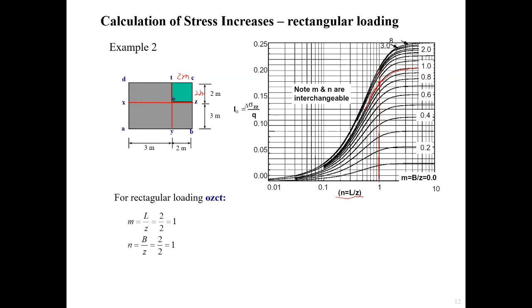So obviously here you have one intersection point. Then you just draw the horizontal line to the corresponding value on the vertical axis. That's the influence coefficient I sigma. The value should be similar, just a bit of difference. So that's 0.175, somewhere here.